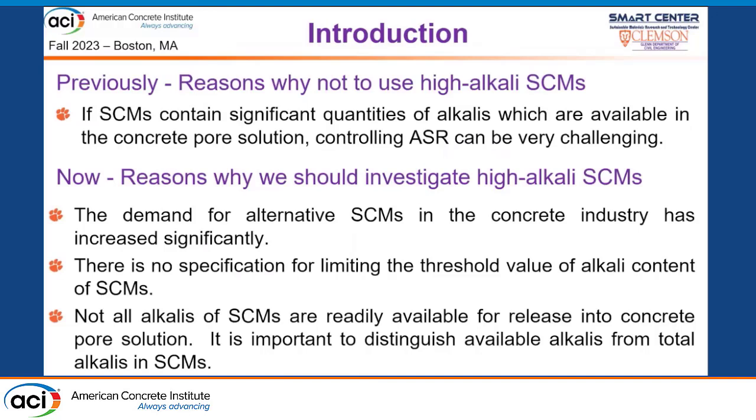Previously, the high-alkali SCMs were not recommended for use in the concrete industry because the alkali content is believed to release into the concrete pore solution, which makes it more challenging to control the alkali-silica reaction. But right now, because traditional SCMs like fly ash are running out, the demand for alternative SCMs in the concrete industry has increased significantly, which provides the motivation for our study.